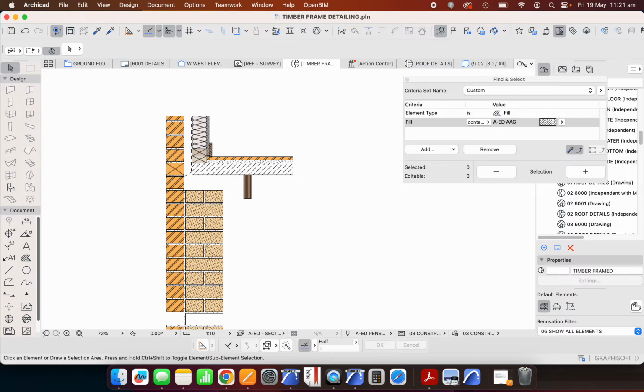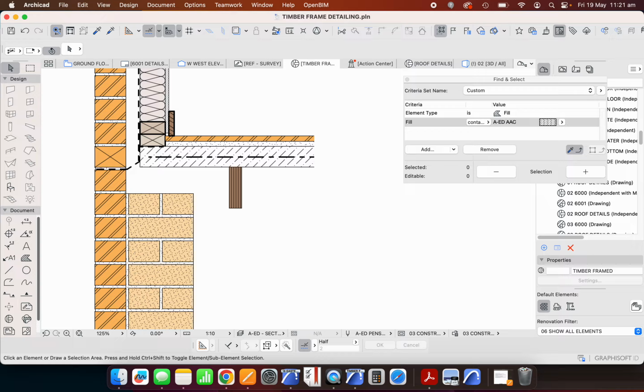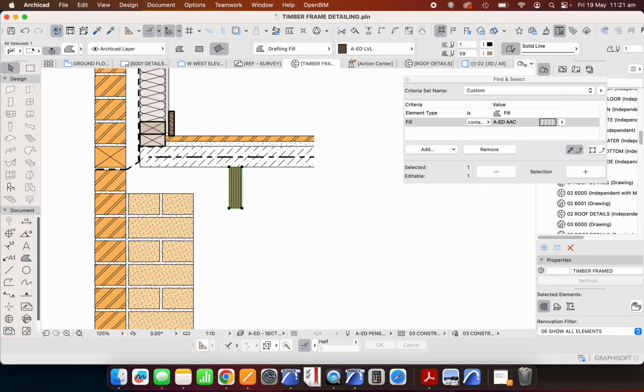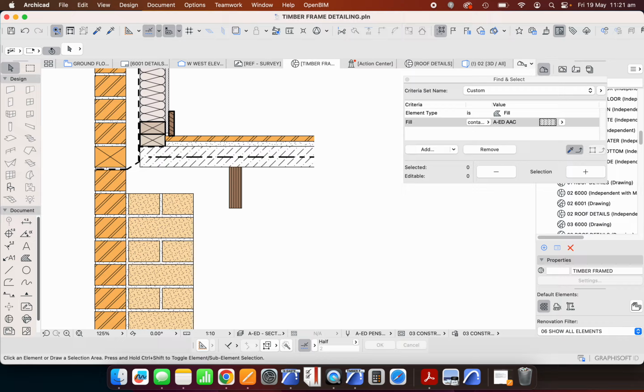Now, before I started this, we were talking about what depth of joists, what spacing of joists, what depth of bearers, what spacing of bearers. And so what we're doing here is we're using span tables provided by Carter Holt Harvey for their Futurebuild LVLs. I'm not including this in the tutorial just to keep it all focused on drafting, but this is where we're getting the information from.